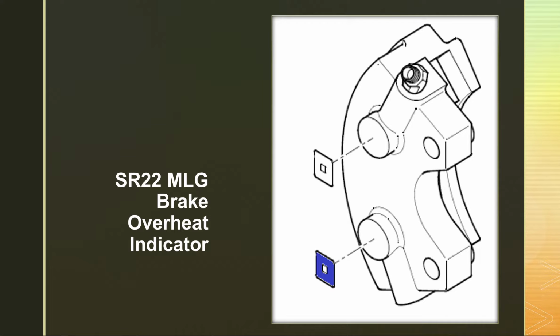Now, thanks to that, they can only turn so much into heat before they catch on fire. They just don't work anymore. The brakes start to get mushy, and then the brakes start to fade, and then the brakes don't work at all if they get too hot. So if you drag your right brake all the way to the run-up area, and then you take off, your brakes are already hot, and they might not work as well for you if you have to abort that takeoff. Or they might not work at all.